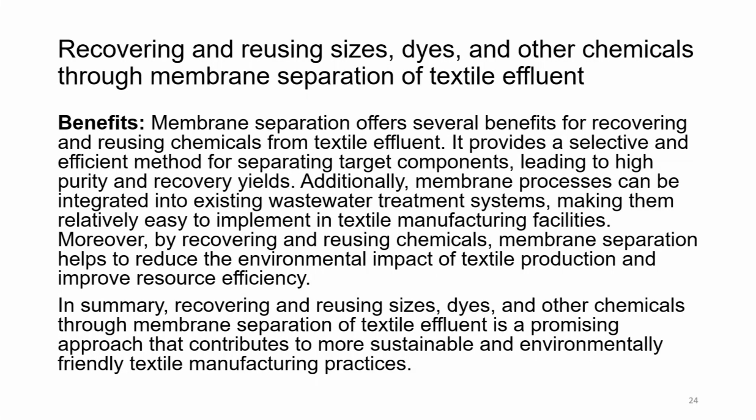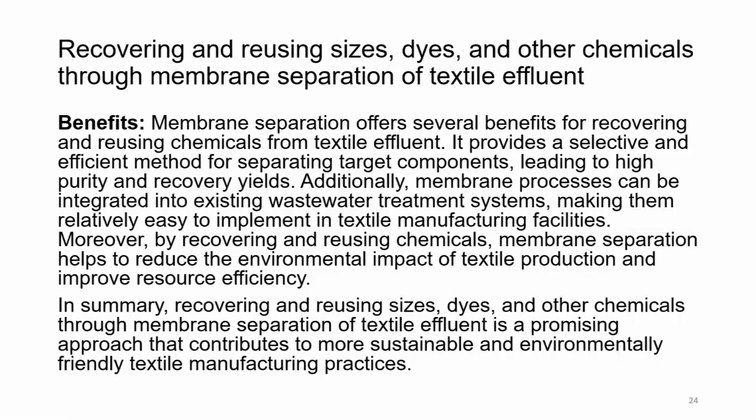So, what it means is that membrane processes are very good. There are lots of benefits. The only drawback is the membrane fouling, which can be overcome by cleaning periodically and maintaining it. In summary, recovery and reusing of sizes, dyes and other chemicals through membrane separation of textile effluent is a promising approach that contributes to more sustainable and environmentally friendly textile manufacturing practices.